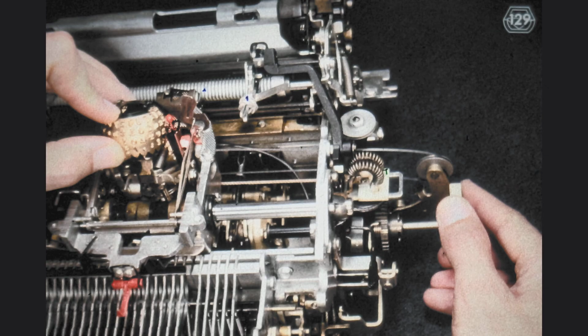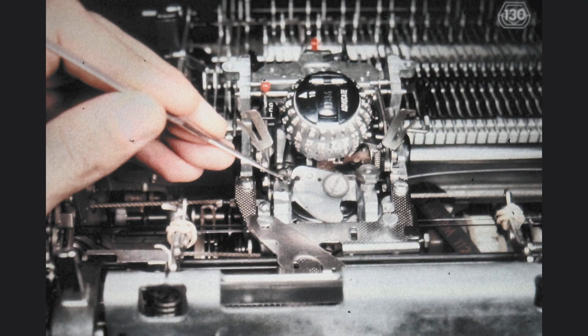First, hold the element in position while you complete the half cycle that was locking the element. Then slowly release the spring tension, watching very carefully the whole time that the tape does not come off any of its pulleys. If you haven't already done so, reconnect the tilt spring at this point.